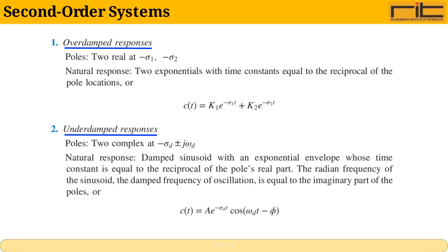These systems are characterized by differential equations where the highest derivative is of second order. Unlike first-order systems, second-order systems can exhibit more complex behaviors such as oscillations, overshoot, and damping effects. Understanding these dynamics is crucial because they appear frequently in engineering applications, such as mechanical vibrations, electrical circuits, and control systems. By studying the response of these systems, we can predict how they will behave under different inputs, which helps in designing stable and efficient systems.